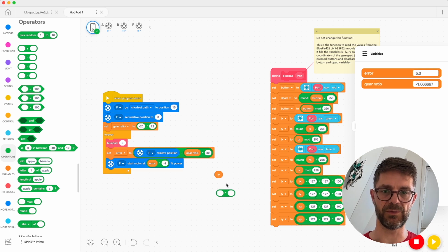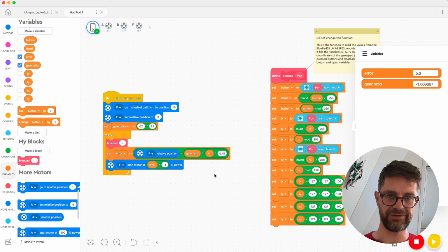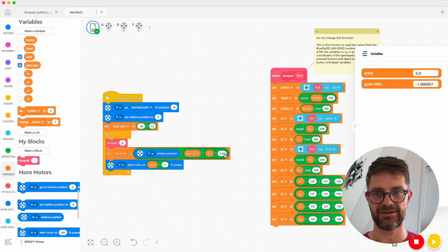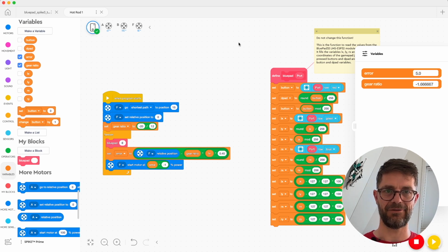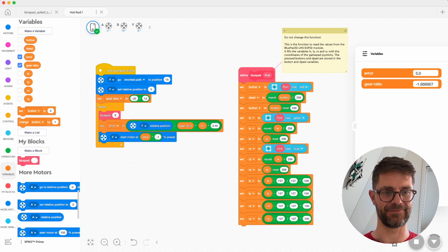But the steering wheels don't go that far. So let's make it like 45% of the original value. Left stick. Oh no, it was going to be the horizontal left stick, so that's LX. Good. So that's 45% of 100. This is going to generate a number of -45 degrees to +45 degrees, and it will be a nice steering wheel. So let's see if all of this really works, and run the program.